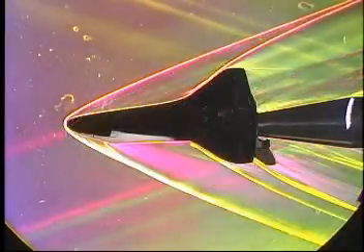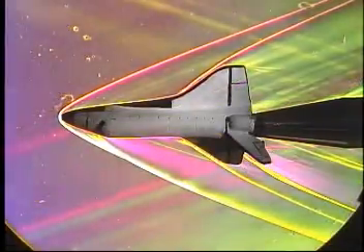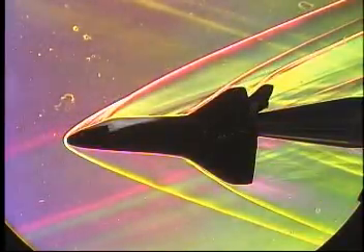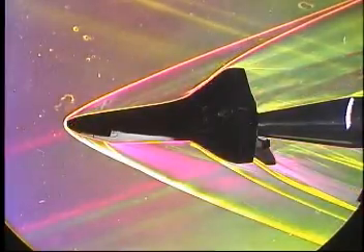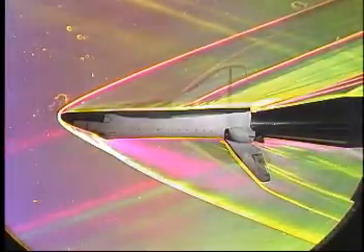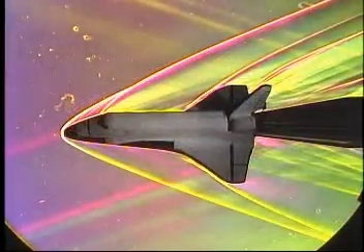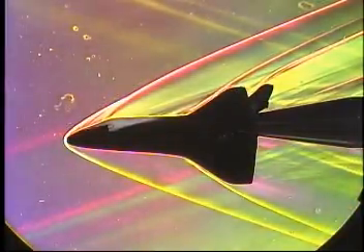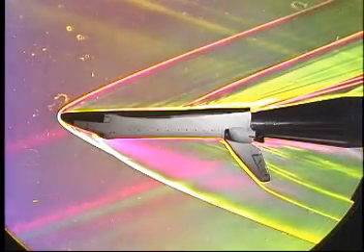That's the case for the envelope of shock waves that surrounds this model of the Space Shuttle orbiter, here being tested at Mach 3 in a supersonic wind tunnel and imaged using a color Schlieren technique. Despite the complicated nature of this flow, we can still use approximate methods of fewer dimensions locally, such as a 2D flow approximation at the wing leading edge, to help understand the basic fluid dynamic building blocks that combine to make up real, practical flow fields.